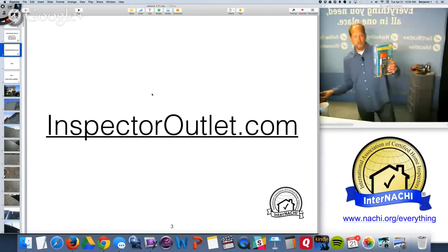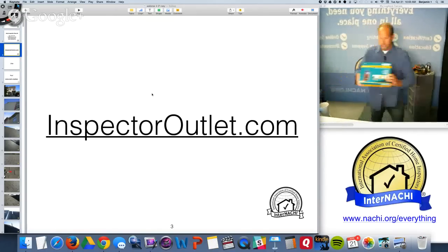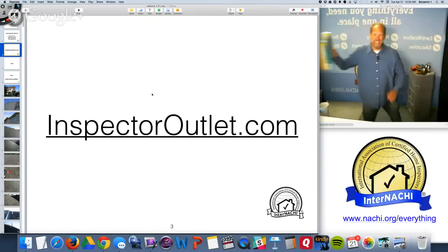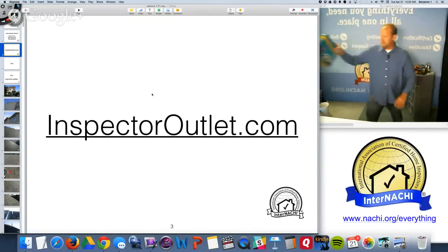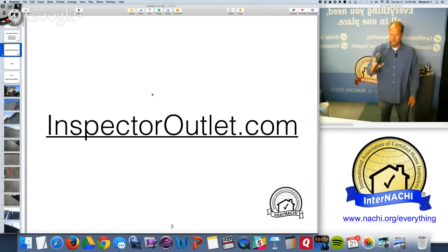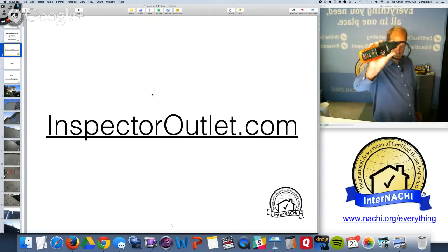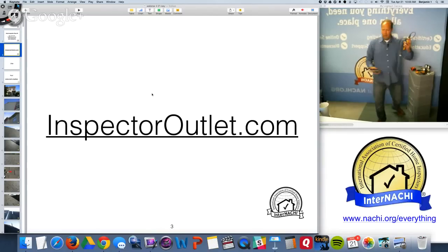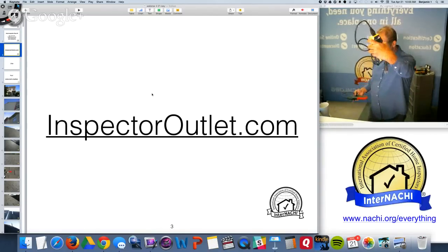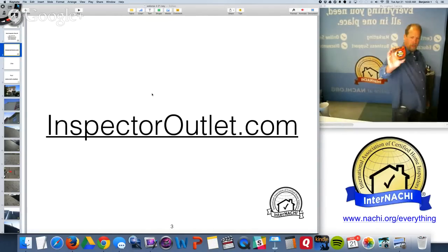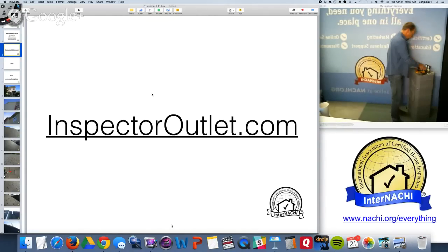There's another moisture meter. It's a dual moisture meter. This one's really good if you're into indoor air quality. That's a humidity moisture meter. Like if you're in an attic and it feels humid up there, maybe there's a dryer vent exhausting into the attic and you're not quite sure, you want to come down with a moisture meter, humidity meter to show your client. Here's a GFCI receptacle tester, AFCI tester. That one's from X-Tech. I used to use Ideal, the yellow one. I like to measure the approximate depth of the insulation in the unfinished spaces. You're actually required to do that.